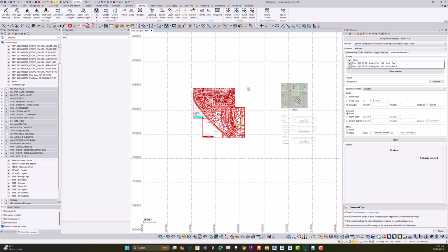So if we build a surface model from this data in local coordinates, and now we've moved it into global national state plane coordinates, at that point now we could take that surface model and put it on the machines and use it for rough grading. We could use it for rough staking. Even though it's come from a PDF, it's good enough to get your rough grade stakes in the ground. And then once you've got the machines rolling, you can then go finish up your model from the CAD data that you've now been provided with, overlay that on top of this, or build it in a separate file and reference this one in as a reference, and then you've got all the information you need for the project to actually go into field operation stage and get moving.